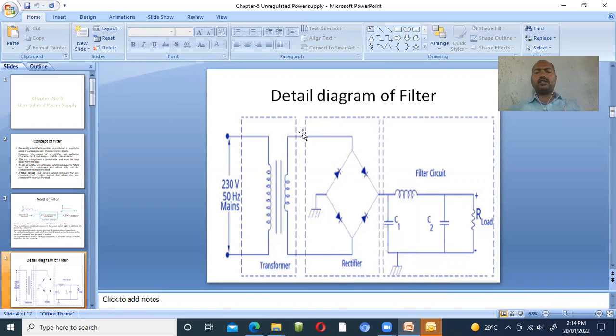So during the second half cycle, whatever voltage is applied across it should be reversed, because AC has two half cycles, right? So minus is coming across here, plus is coming across here. So the minus voltage affects the diode; see, this diode is already working, and this one is not working now. So a reverse voltage appears across it. This is considered as diode D3, and plus voltage is coming across here. So D3, D4 is working.